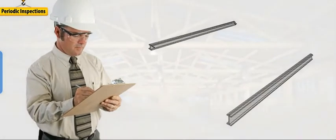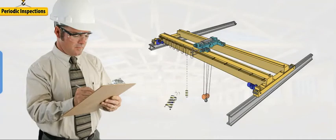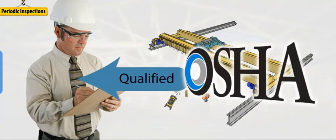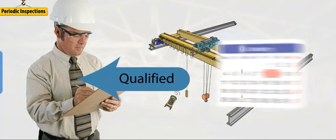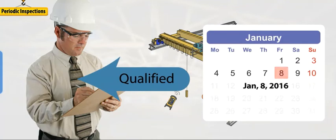Periodic inspections typically include the beams the hoist rides on, crane and hoist ropes, pulleys and drums, brakes and bearings, and even bolts and rivets. Annual load testing of your company's overhead and gantry cranes is a type of periodic inspection. OSHA requires that crane and hoist ropes be inspected by a qualified person at least once a month and must be certified with the date of inspection, identification of the ropes, and the inspector's signature.